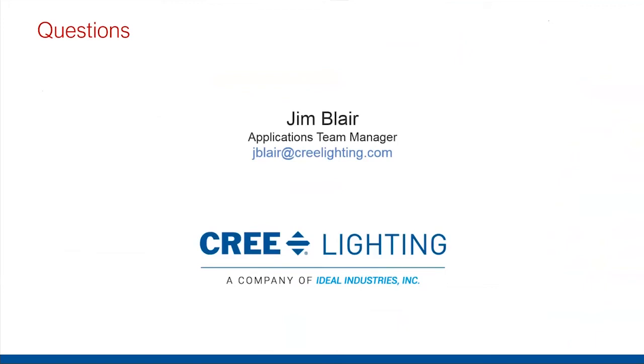Absolutely. So we find that the lumen maintenance factor, as you well know, is really the differentiator with some products. And we have light loss factors that we can assign for each of our products that showcase values after 50,000 hours of operation, or even in some cases 100,000 hours when fixtures are on for longer periods of time, like a parking garage. In interior spaces, we're typically looking at the 50K column and offering values there.